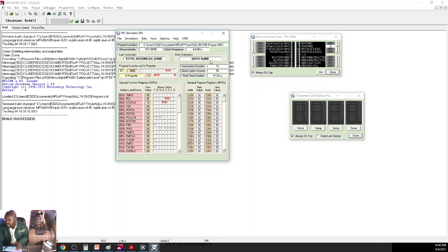Perform ADC, wait for the ADC. And as we perform our ADC, let me just see if I'm going to pick up that value. Wait for the ADC to take place. And then once ADC has taken place, we will have to go and check. Move file address L into W. Address L has 0B, which is 11, right? Which is that 11 there. Clear file result 0, result 1, and result 2. Take 2, subtract it from address H.